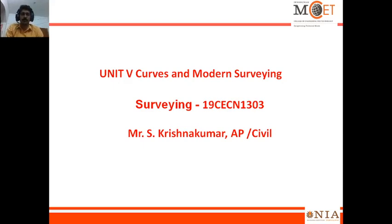Hello friends, next we are going to continue the next setting out method of the curve, that is the angular method. Before that, as a recap for the linear method, we have seen about the radial offset and the tangential perpendicular offset from the tangent. We see a small problem in that.